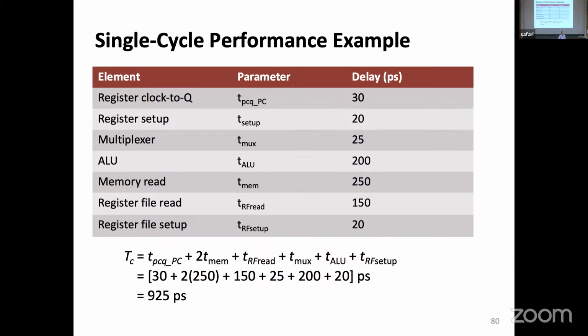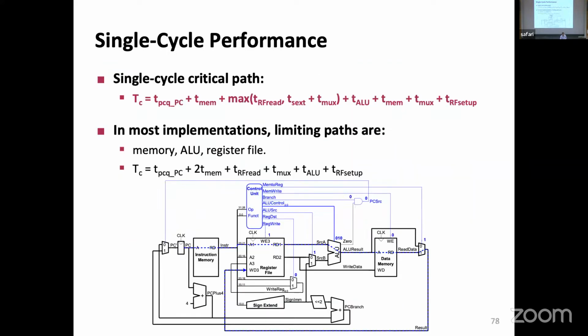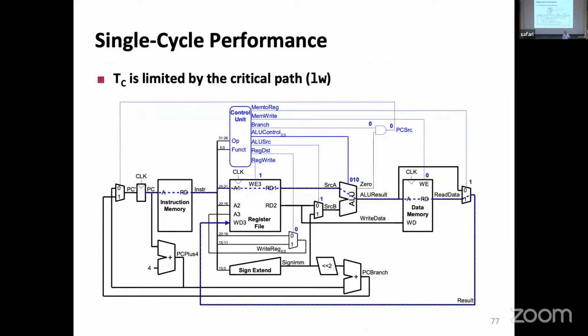Now, I would ask the following question. How do I know this is the longest path? As I said, there are actually tools that can calculate from every flip-flop output to every flip-flop or state holding element input. They can automatically calculate all the paths for you. As a designer, you also know what your paths are.